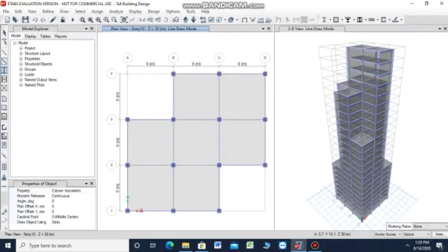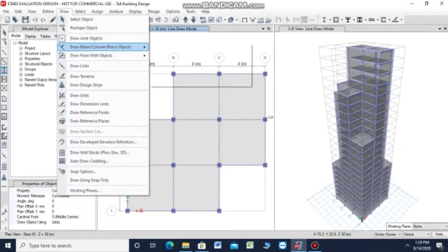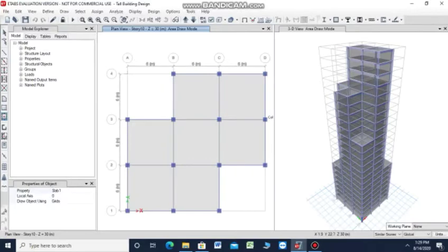And for moving on to the next set of similar stories, that is from story 9 to story 14. The first was from 1 to 9. Now similarly applying the slabs for all these similar sections. We have to select all the different tiles this way. Then we'll move to the story, similar sections like this, and we'll apply.